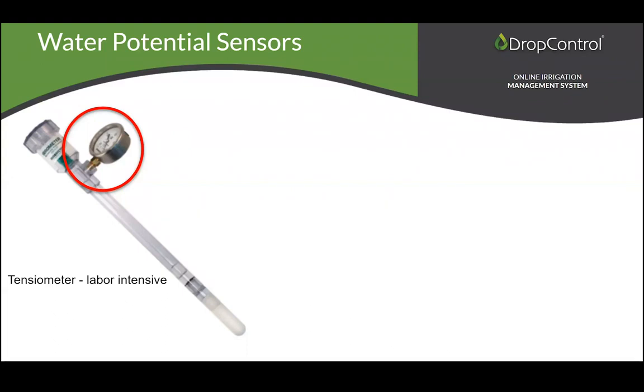into the node or RTU, so we can continuously be reading the tensiometer every 10 or 15 minutes. The problem with the tensiometers is that they're labor intensive. You've got to go out there and fill them with water, and you've got to be constantly handling them and making sure they are operating correctly. So the continuous objective there, if they run out of water, then you stop getting the reading. So the data gets